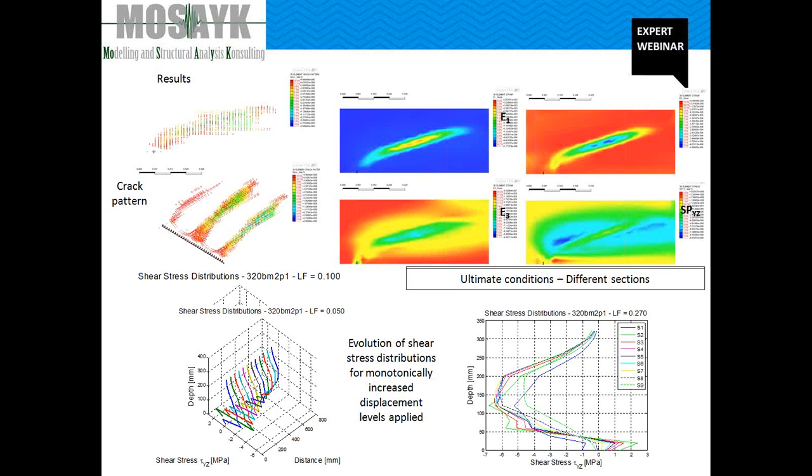Accordingly, a diagonal strut whose width increases as the imposed vertical displacement increases connects the transverse line load and the support. This failure mode results in an incipient change in the shear stress distribution localized at a distance roughly equal to the hollow core depth, where the maximum tensile strain over the whole member is undergone.